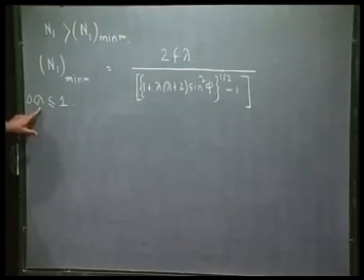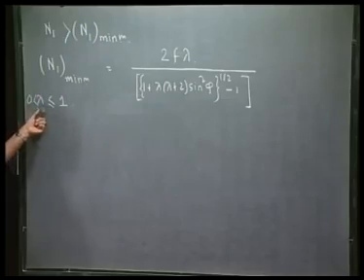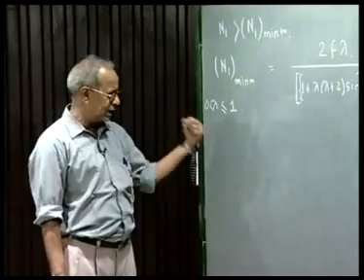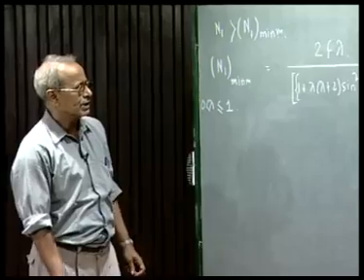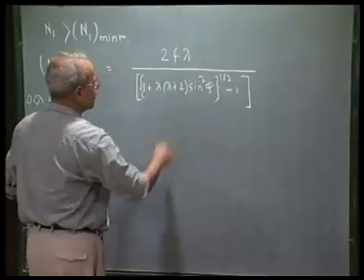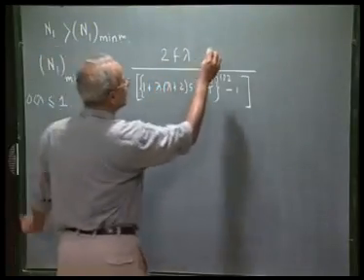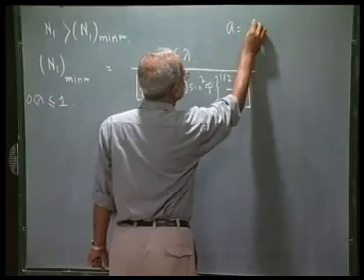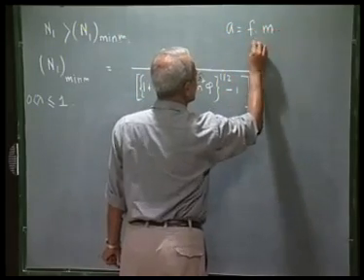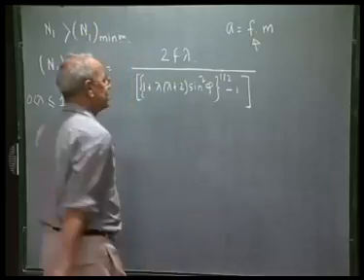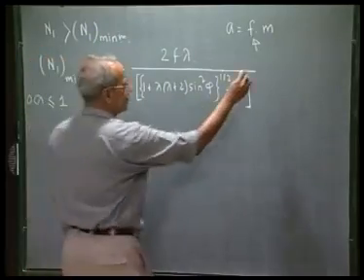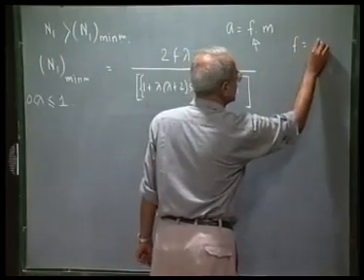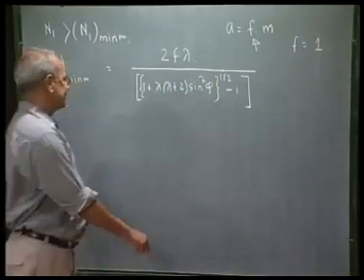We always define lambda as less than 1, that is the slower angular velocity divided by the faster angular velocity, and phi is the operating pressure angle. What is f? f is addendum expressed as a constant fraction of the module. F is normally 1 unless otherwise stated.